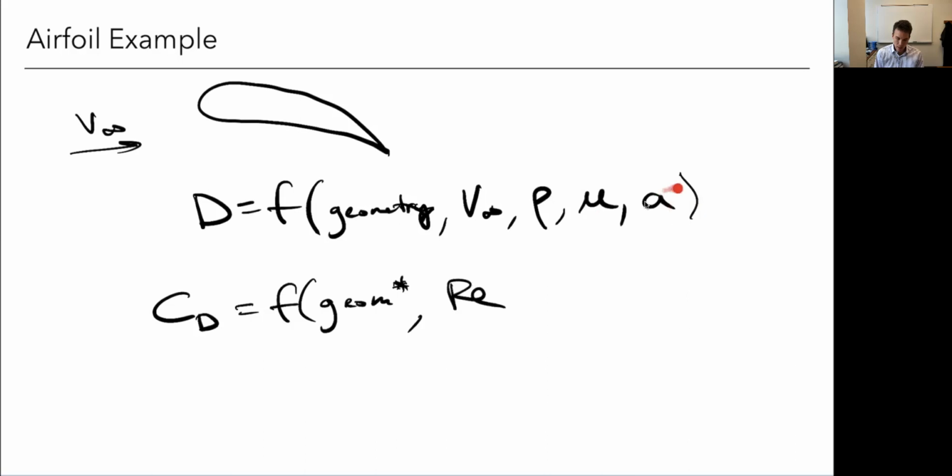Adding the speed of sound will give us the Mach number. And that's pretty much it for almost every aerodynamic application. For a given geometry, these are the most important. And if it's low speed, then just Reynolds number. Sometimes, like that wind turbine one, there are other operational things like the tip speed ratio. But this is pretty much it.